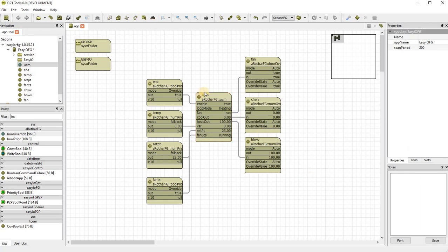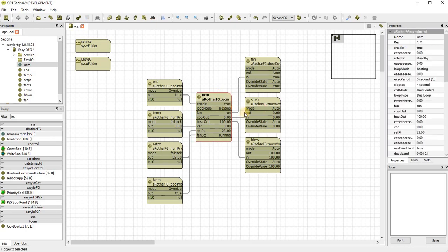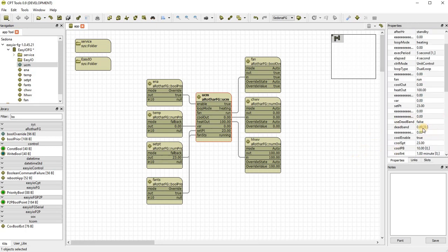To help you tune the loop, sometimes we've found that you can get the integral value right, but 100% proportional action on the output just doesn't balance the loop out and you end up sitting there for hours and hours messing with the thing trying to get it to work. When all you really need to do is reduce or increase the impact of the proportional component.